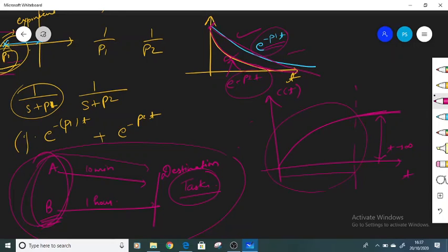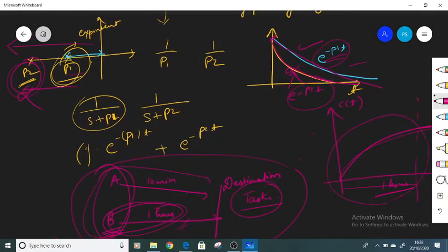तो हम ये transient time जो आ रहा है, ये किसकी वजह से स्लोअर हो रहा है। यहाँ पे ये जो ट्रांजिएंट आपका आया है ये किसकी वजह से इतना आया है। सपोज आई एम सेइंग सेम थिंग, इफ इट इज कमिंग एज 1 आवर, ठीक है, आपका ट्रांजिएंट टाइम जो आ रहा है 1 आवर आ रहा है। अगर ये पोल नहीं होता, ये बी वाला पोल, सपोज यहाँ पे जो आप देख रहे हैं, if this P1 pole had not been in the picture, then the output would have been reached earlier only. आउटपुट जो होता है वो आपका काफ़ी पहले रीच हो जाता है, बट ये P1 की वजह से जो आउटपुट है वो बाद में रीच कर रहा है.